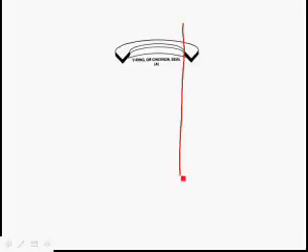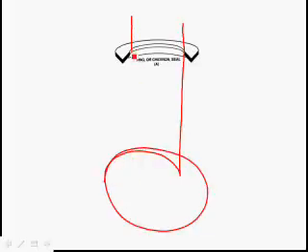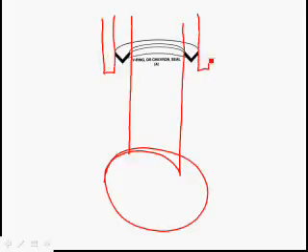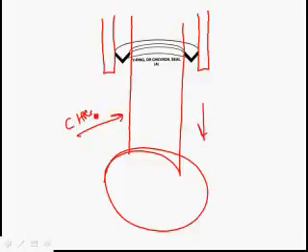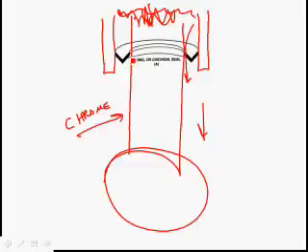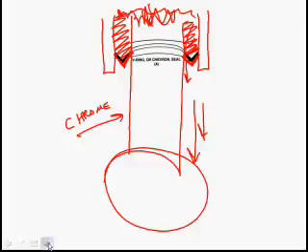Let's say you had a Cessna 172 shock strut. We're all familiar with Cessna 172s. So that nose wheel shock strut goes up and down. You're looking in right here. It's chrome plated so it doesn't rust. And there's hydraulic fluid in here, and the hydraulic fluid would tend to leak out. So they put a V-shaped seal in here so that as the shock strut goes down, it scrapes the fluid off and keeps it inside of the shock strut. So a seal or an O-ring does the same thing.